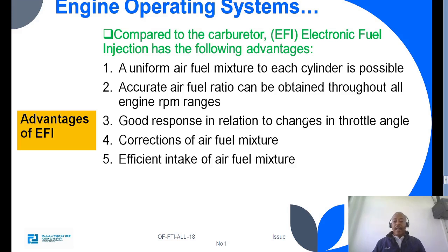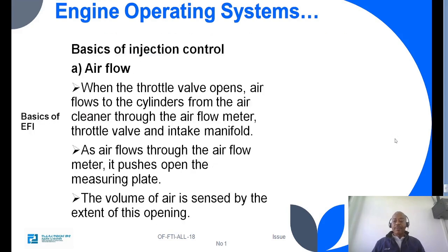Advantages of EFI. Compared to the carburetor, EFI, electronic fuel injection, has the following advantages. A uniform air-fuel mixture to each cylinder is possible. Accurate air-fuel ratio can be obtained throughout all engine RPM range. Good response in relation to change in throttle angle, correction of air-fuel mixture, and efficient intake of air-fuel mixture can be achieved by using EFI.